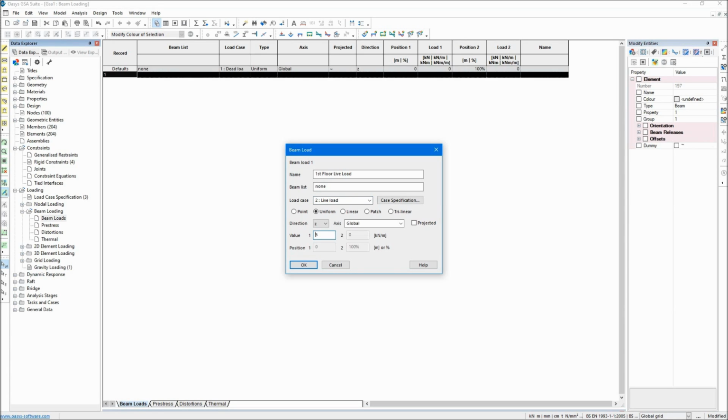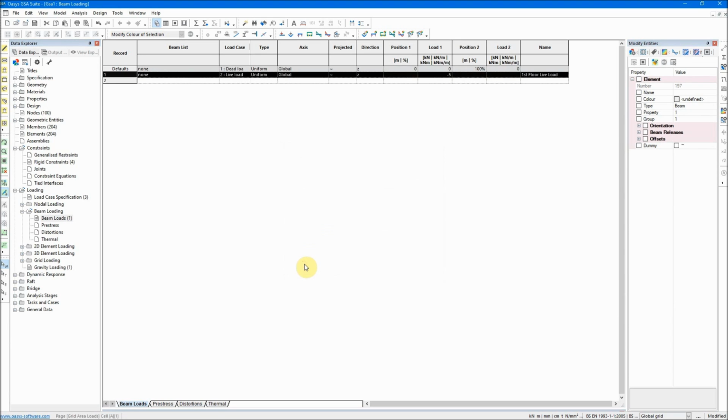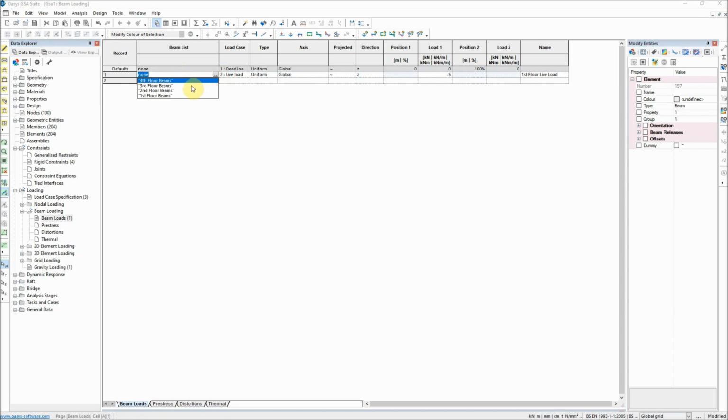However, I will put a negative behind it, indicating that although the direction of my Z is going from bottom to top and is positive, I want it to go from top to bottom, meaning in the direction of gravity to the center of the earth. That's why I'll put a negative behind it, so it goes from top to bottom. I'll click OK.